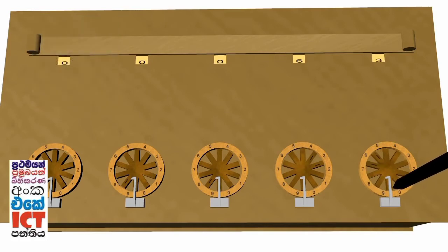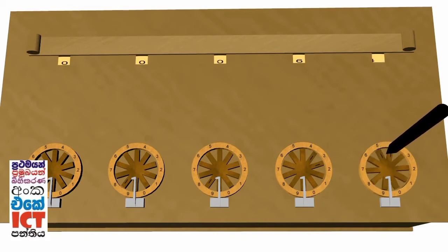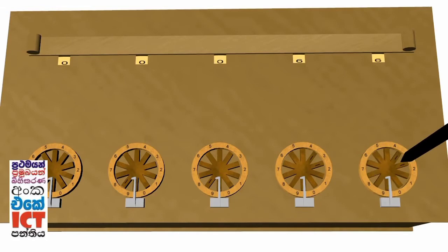The values stored in the Pascaline must be cleared before a new series of additions can be performed. Clearing is done by setting all the accumulators to 9 and then adding 1 to the lowest order digit. Setting each accumulator to 9 can be accomplished by inserting the stylus between 2 specially marked spokes and turning the input dial all the way to the metal stop.